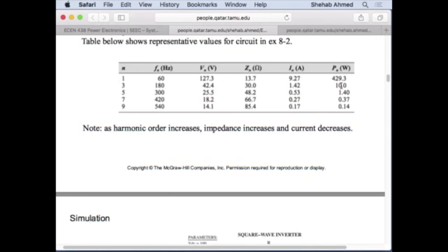That's why I was trying to explain that. In an RL load, it's not very clear. Okay, fine, I'm generating real power, what's your problem, right? But if I'm applying this to a machine, then it's a problem. That's why I would like to improve it. The biggest chunk of industrial loads are motors, so that's the justification. You cannot live with low-order harmonics that are producing power, because then you're going to be heating up motors unnecessarily without producing the torque that you require. You're going to have to derate all your equipment, which doesn't make sense. You derate transformers, derate motors, etc.